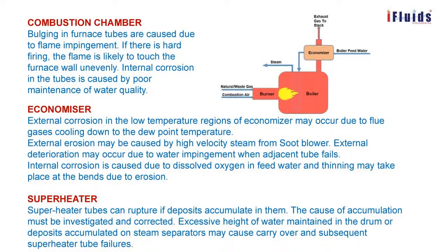Combustion chamber. So this is the natural gas with the combustion air inside. It is burning by igniting. It burns, and the boiler, the downcomer, and the riser are coming here. The economizer is a boiler feed water preheater. It is coming in. These tubes are being heated up.